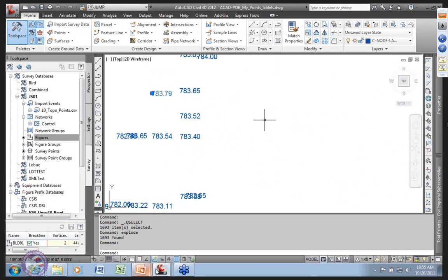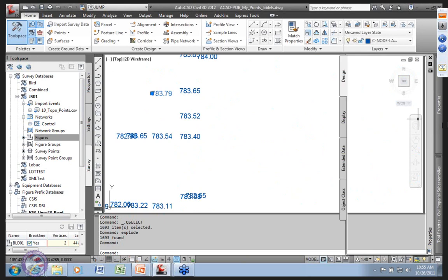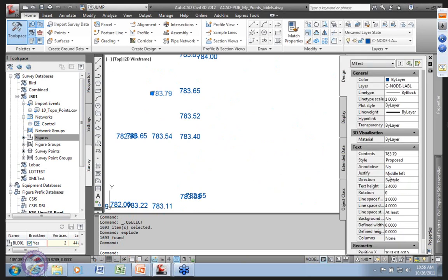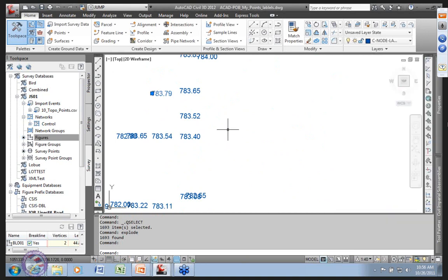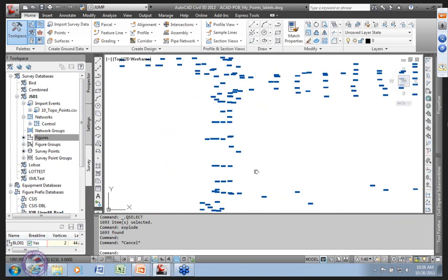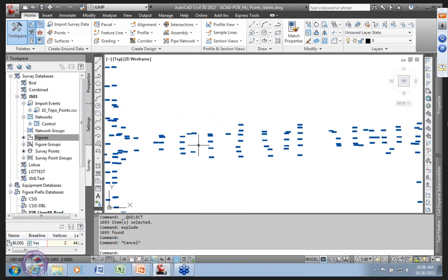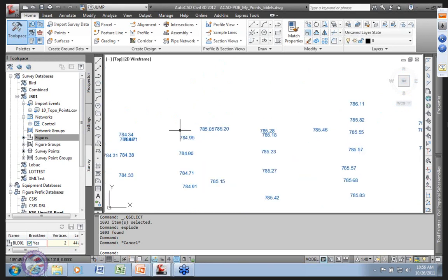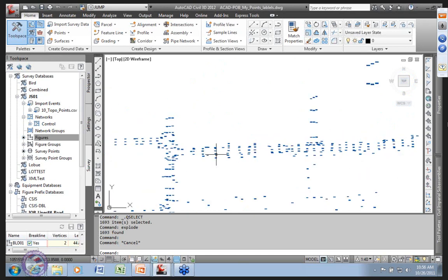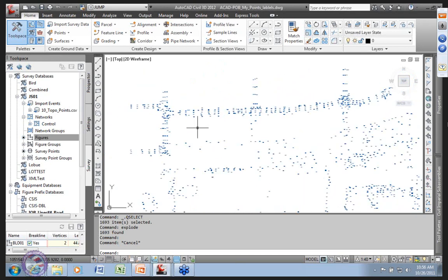Okay, and we're doing an autosave here, and you will see now they are a classic MTEXT label, right? With whatever style you assign to the label and all that other stuff passes through. And so now you've got an elevation label at every single one. This could have been a whole range of different labels determined by point group, expressly rotated the way you want them. All that stuff is just detail mechanics with the labels.